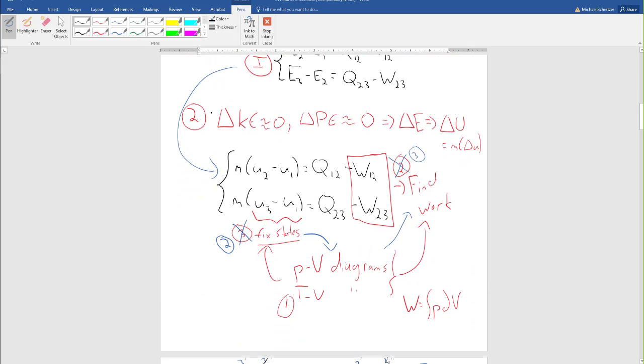I have a quick question. Shoot. When you're approximating because it's a subcooled liquid, you can do that for all of the different properties, right? Like enthalpy and specific volume. Yes, except for temperature and pressure. But all the other properties, that's reasonable to do. Okay, all right, thank you. You're welcome.